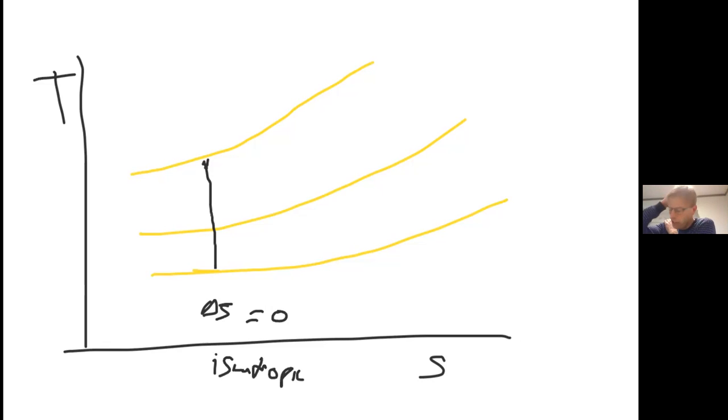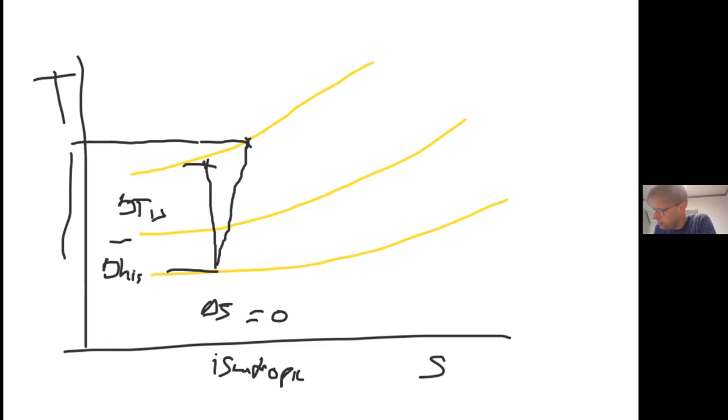But in reality, we don't have isentropic. We have all kinds of losses due to friction, all kinds of stuff. And there you get something like this. And important to know is, like I said, this is delta T isentropic, which is more or less delta H isentropic, if you have a constant Cp. And you see here delta T real. For a compressor, it's important to know that the real work required to compress a fluid is higher than the isentropic.